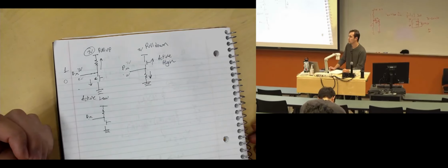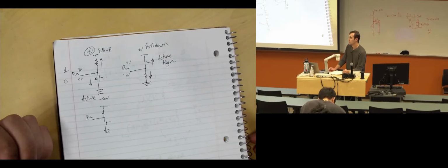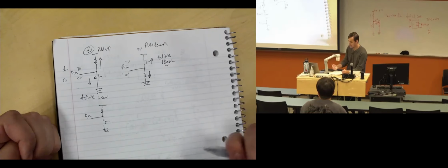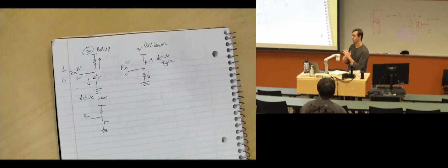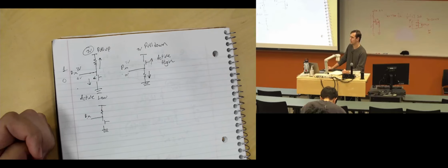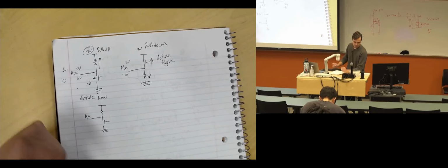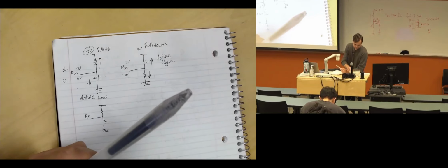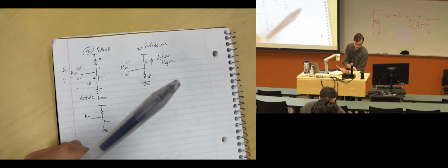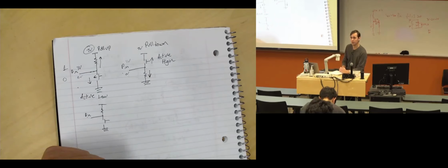So not being acted upon, basically the switch just acts like a high impedance, so no current will pass through. Exactly. It's not connected. What switches literally do is connect two pieces of metal and allow current to flow. So yes, exactly like that. Any other questions about pull up, pull down?